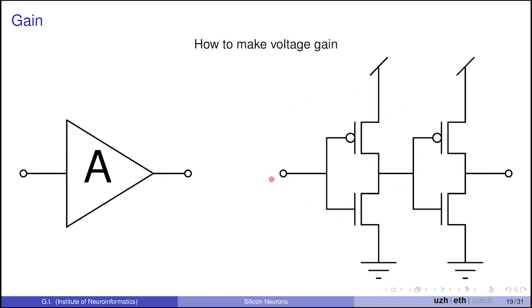Basically, if your input is low, the output is high. And if your input is high, the output is low. It's just an inverter. And this is actually what was done in the early 90s to implement the Axon Hillock circuit. And again, a historical note is that when the Caltech team developed the chip that implemented this circuit, in the end, when they got the chip back, it was burning a lot of power.